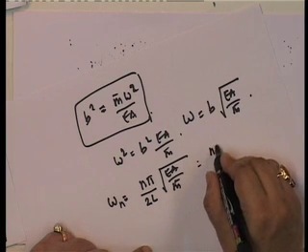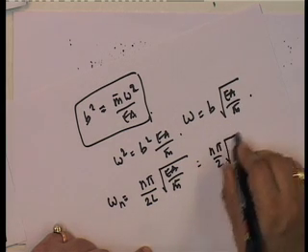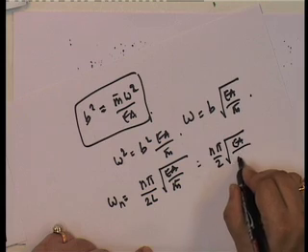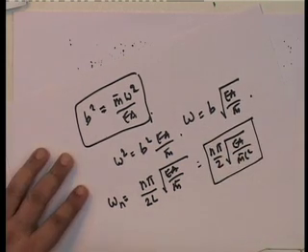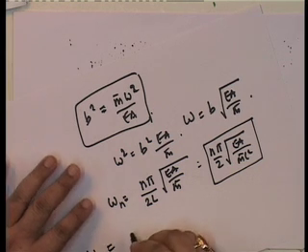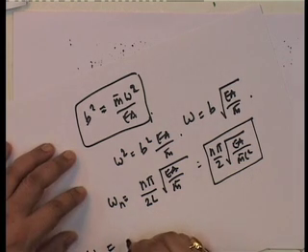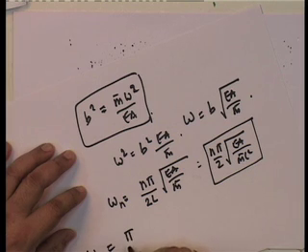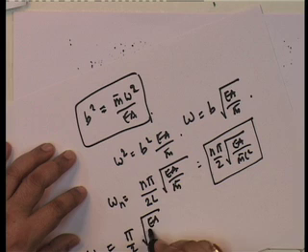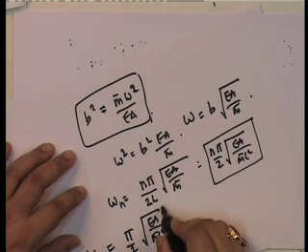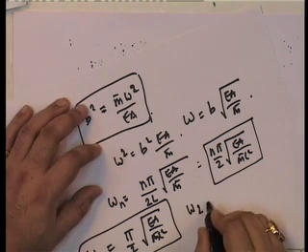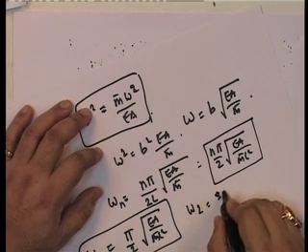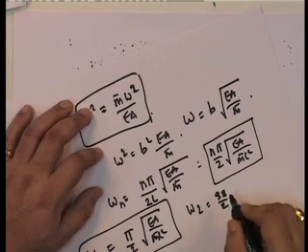So, this becomes n pi by 2 into square root of EA upon m bar L squared. So, omega 1 is equal to pi by 2 square root of EA over m bar L squared. That is omega 1. Omega 2 is equal to 3 pi by 2,